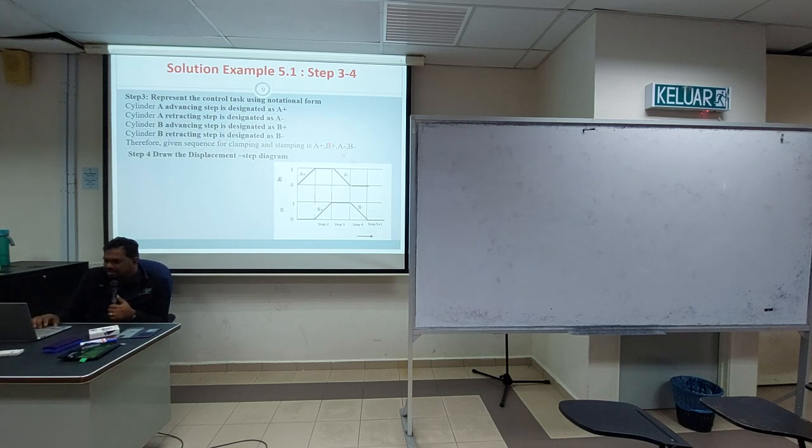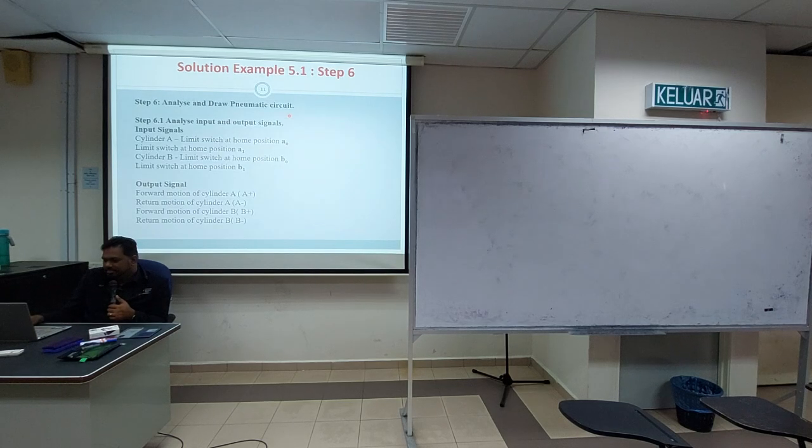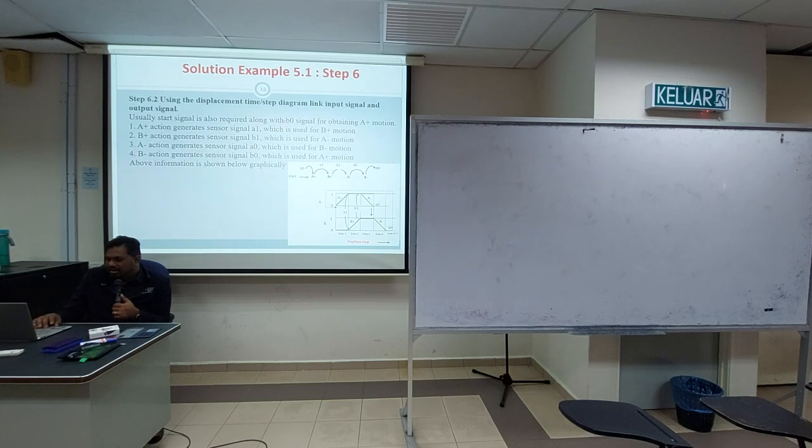Okay, displacement step diagram. If it involves time, you can do a displacement time diagram. Then this is important also: input signals. Where the input signals for the circuit are coming from, and also the output signal. Yang ni you gabungkan input signal dengan output signal. But later in my steps we will straight away go to the motion diagram. I will teach you how to draw the motion diagram.